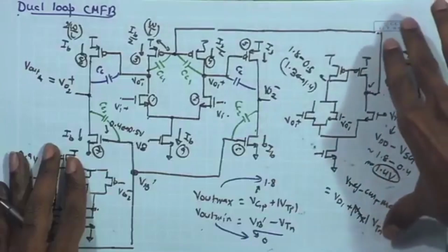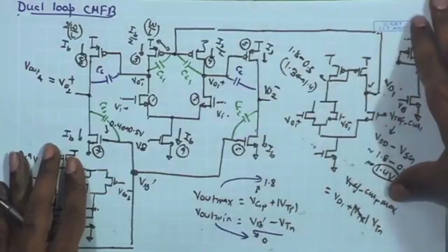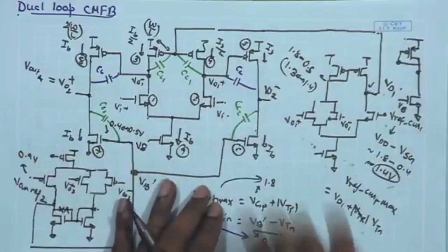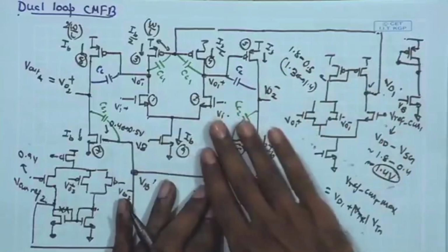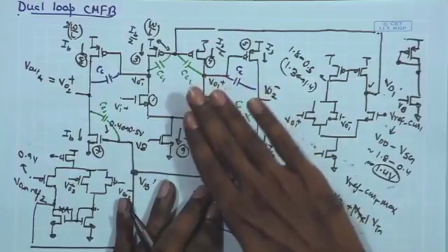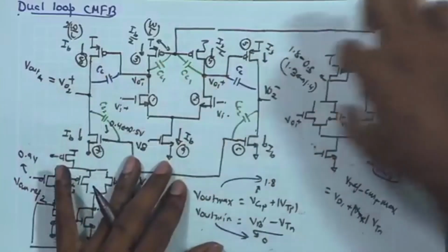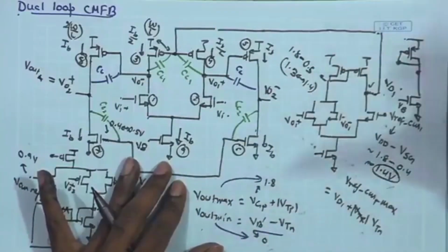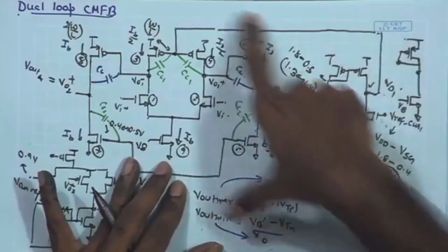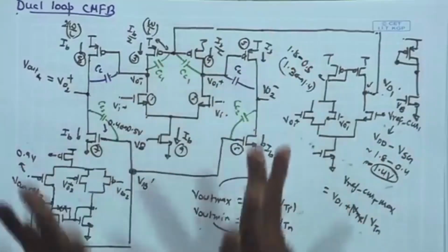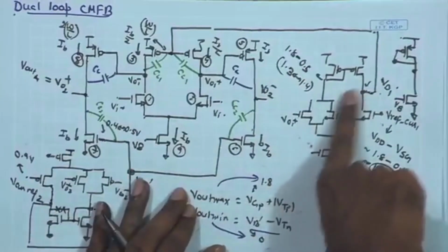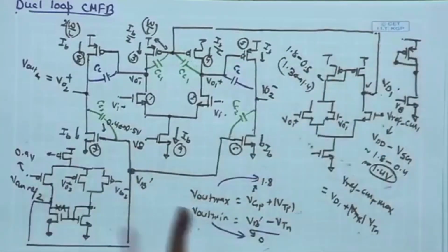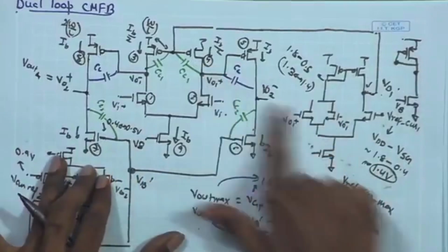So, if I revert back to our previous discussion on single loop, we argued that to keep the overall loop gain for the common mode feedback within a reasonable value, we would like to keep the error amplifier diode connected. So we would replace this current mirror load by the diode connected load, so that the gain of the error amplifier becomes unity, and then traversing the loop you have overall GMRO square gain. If you keep this current mirror load, then for the two loops we have GMRO whole cube, and then the compensation and stability can become more challenging for the